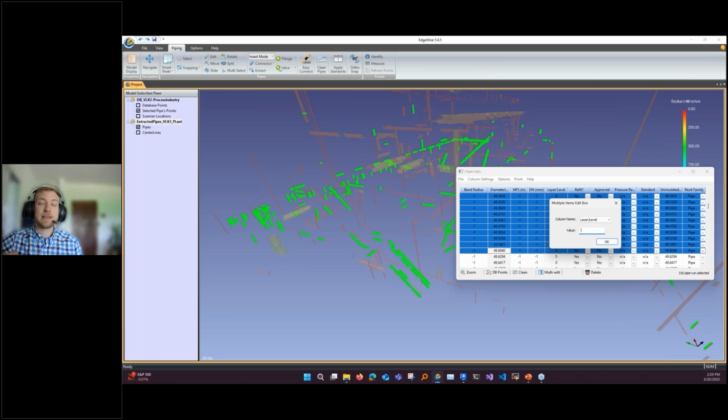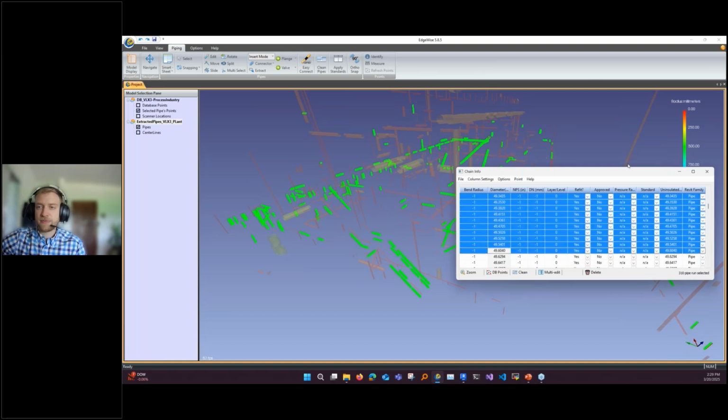It's something that you can do right up at the front, but that's less common. But it's a really powerful tool for other approaches, like if I want to break up my ducting systems and my conduit, or if I want to get more fancy with any system. If I want to say these pipes are in one group and these pipes are in another group, I can physically separate those models to organize things in a different way. So that's definitely a more advanced option.